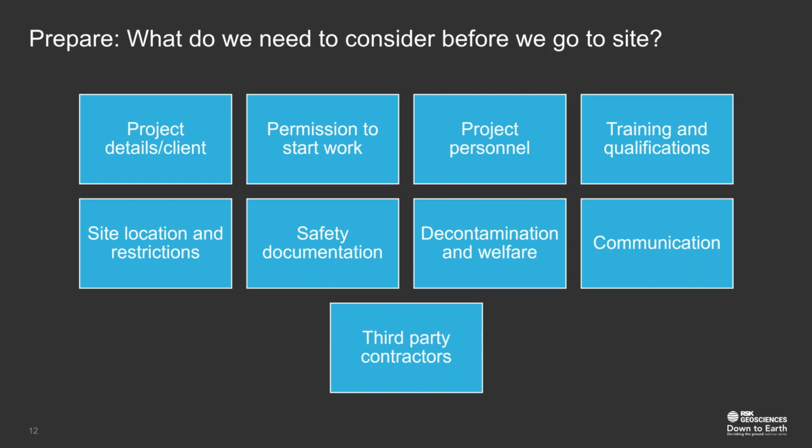Safety documentation, won't go into too much detail, but you need to make sure you've got the two main things, risk assessments and method statements, outlining what tasks need to be done and the risks and mitigation measures associated to do them. Depending on what you need to do, you might also need to consider permits to dig, hot works, working at height, or COSHH assessments, but it's all very specific to your site.